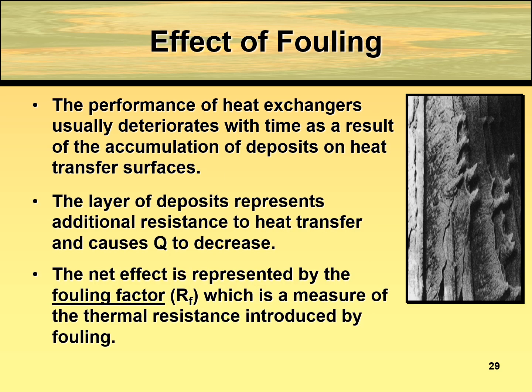Now fouling: you imagine that throughout the year you have a tube running with a fluid, then the fluid will have some resistance, and the surface of the tube is not smooth. As time passes by, debris or deposits will attach to the surface of the tube, then this deposit will give a scale to the surface and will increase throughout the year.